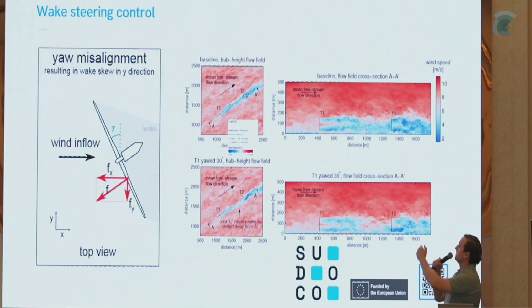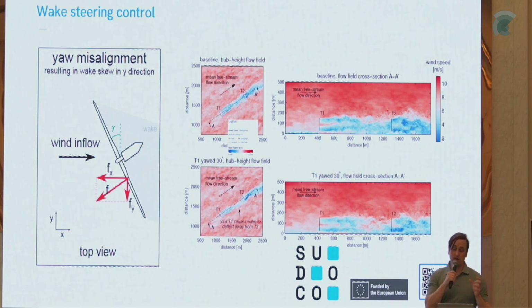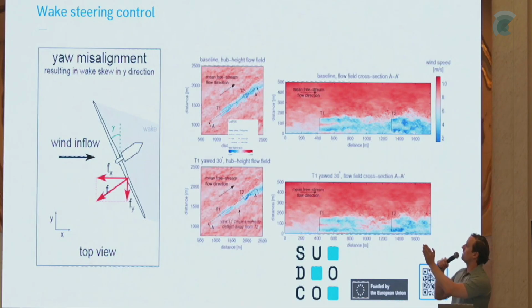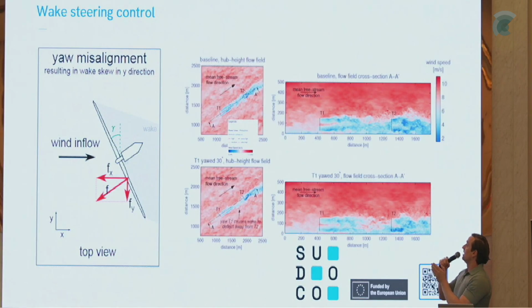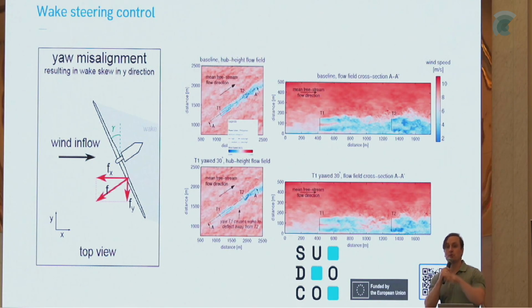What we call wake steering means exactly that we look at the TI values, we look at the inputs that you have, and we simply yaw the turbine a few degrees. So we essentially make sure that the second line has less deflection from the first row, and this means also that the first turbine will have less power. But in total, we're looking at the overall wind farm.